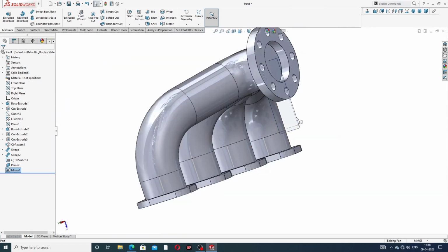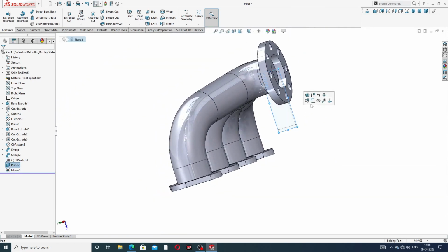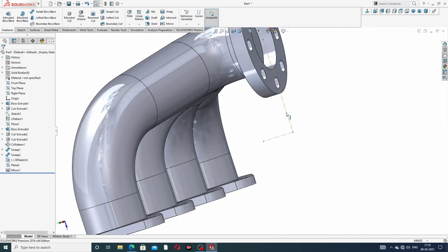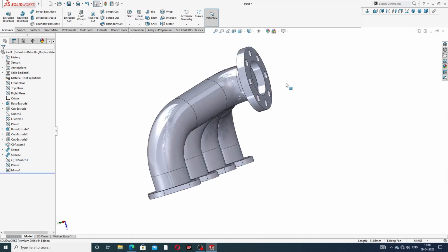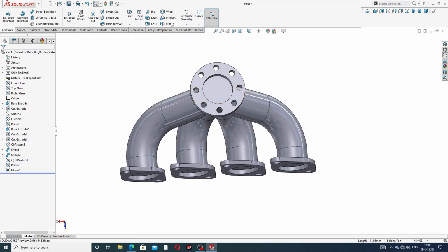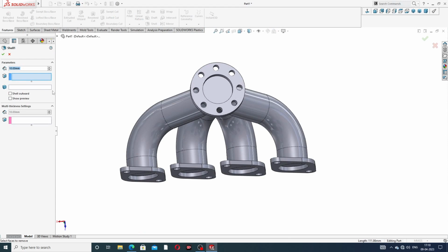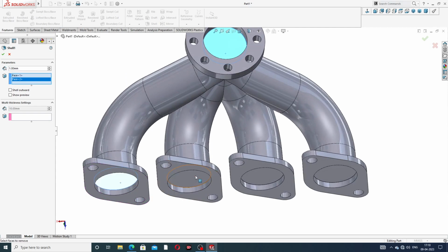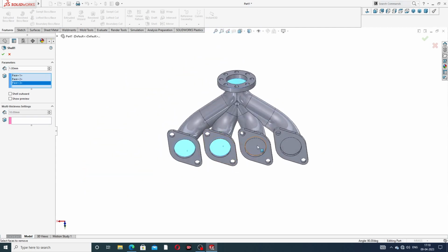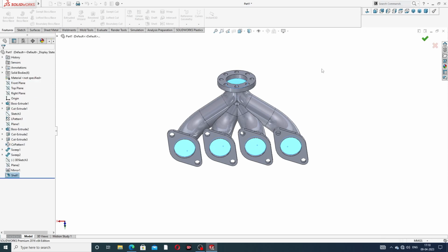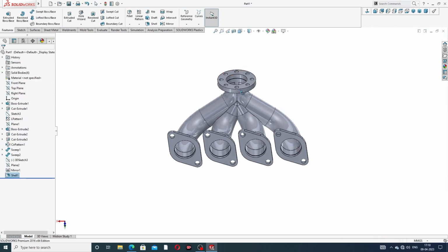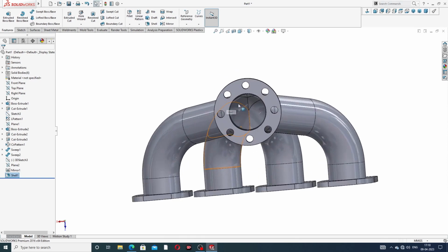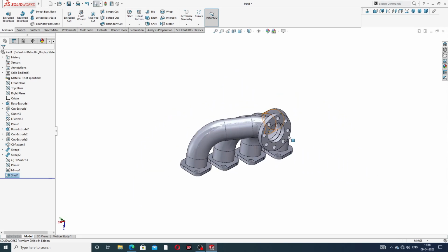This body is correct, and both are hidden because this body looks perfect. Use the shell command here, with a thickness of 1 millimeter. Select this, and select all faces, 1 by 1, here, and click OK. All is hollow, and all looks perfect.